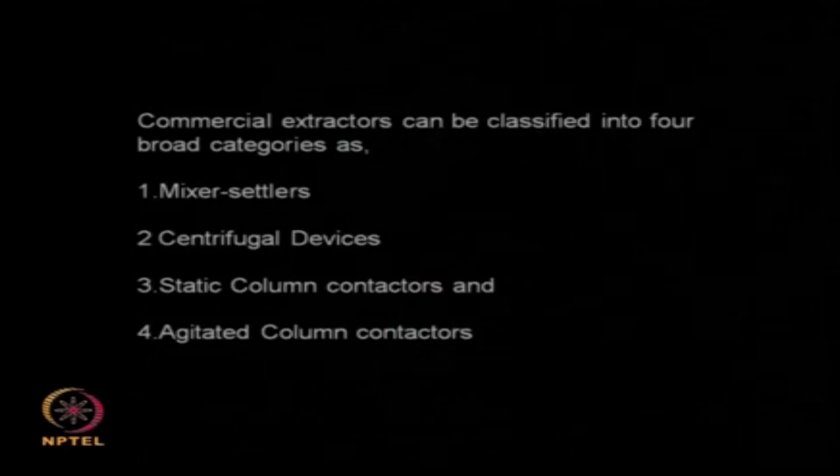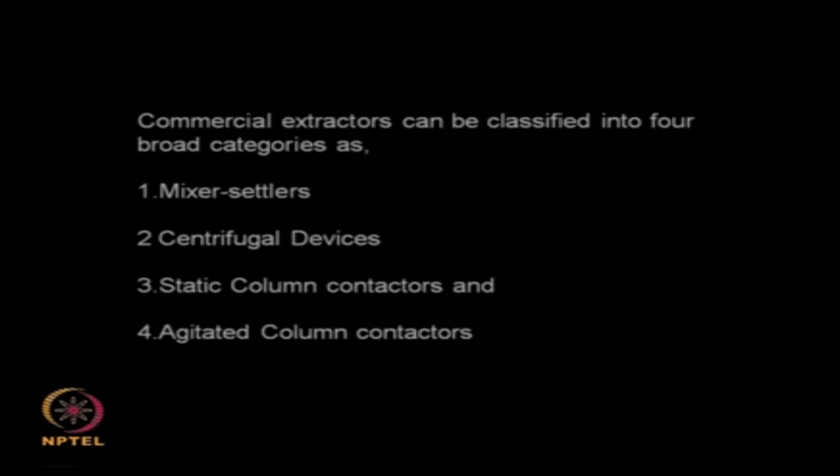So these are the 4 types of designs which we employ on an industrial scale to achieve a good liquid extraction. Each of them has advantages and disadvantages. If you go for a mixer settler, the floor space will be very high. If you go for a column design, it occupies minimum floor space.